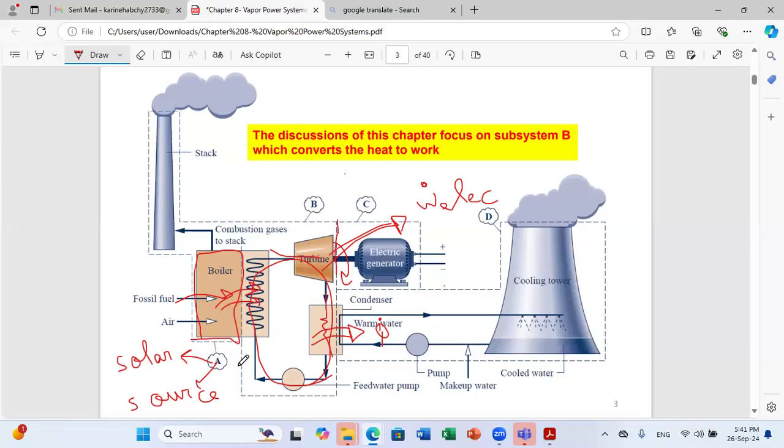And then at this level, it's also very important to profit from the heat lost. So here you have Q dot out. If you don't do anything, you will lose it. So you need to extract this heat for a useful application. We'll see, for example, that you can pass another fluid here. Also, the condenser is like the evaporator, it's a heat exchanger. So at this level, your refrigerant will reject heat. You can pass water, you can pass gases, etc.